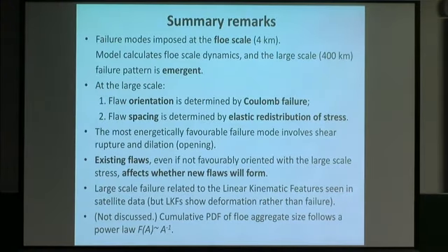So just let me summarise that before I move on to the large-scale modelling. So we imposed a shear rupture or Coulombic failure mechanism at the floe scale. And at the emergent scale, the scale of the domain, we found these floe aggregates. The floe orientation was determined by Coulombic failure, spaced by elastic redistribution of stress. We tended to find a preferential deformation which involved shear and some dilation, okay, which is a very common feature of granular materials.